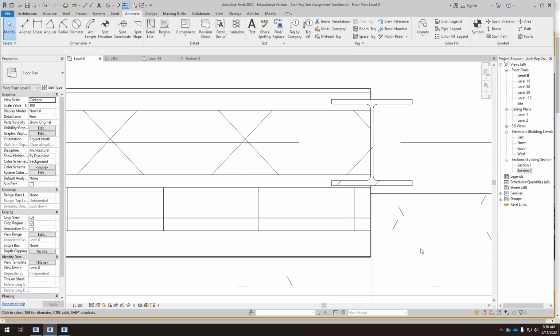And we have another layer here, which is totally fine. I mean, we can have air layers. Adding air to a wall increases the thermal insulation, so it's not something wrong. It's only that this thermal insulation is not attached to this concrete masonry unit, and there's a 1 inch air gap, so it's acceptable. And here I made sure that this air gap again doesn't affect here.